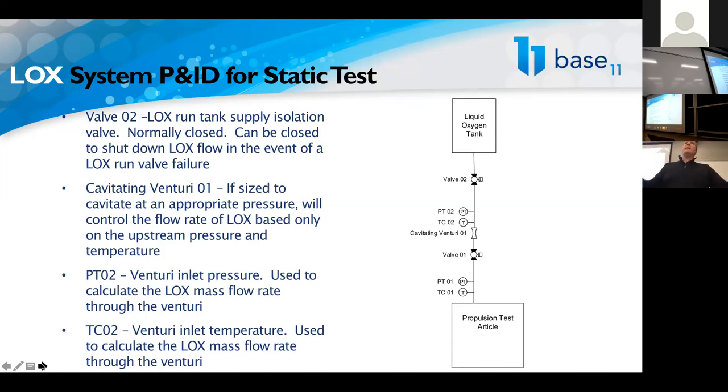It's a really awesome device. It basically allows our propulsion devices to function. But it's a cool device to use in a ground test propulsion system because it allows you to very precisely control your flow rates by simply using your facility pressure regulators to control pressure. Well, there's a similar device for liquids called a cavitating venturi. The physics are different, but functionally it's the same.